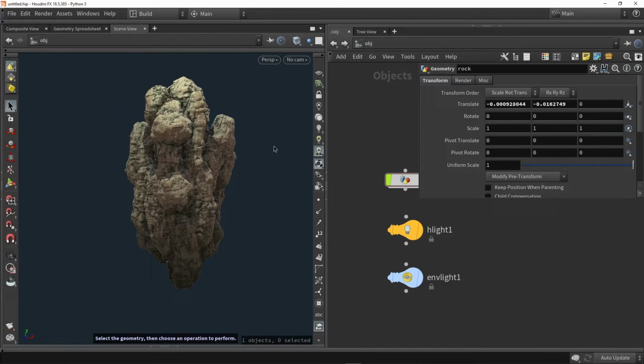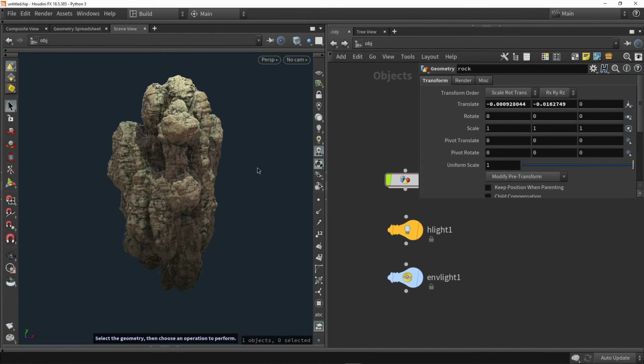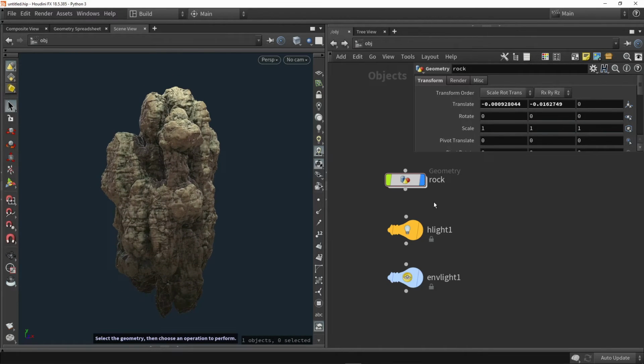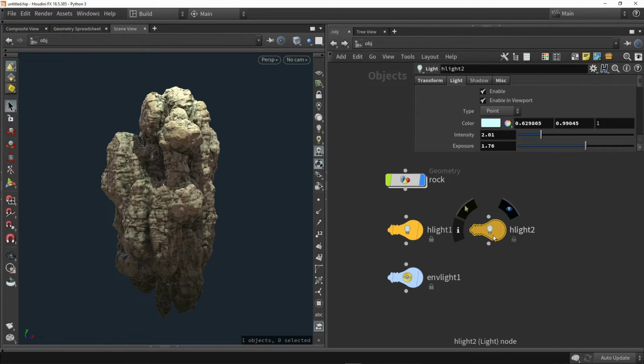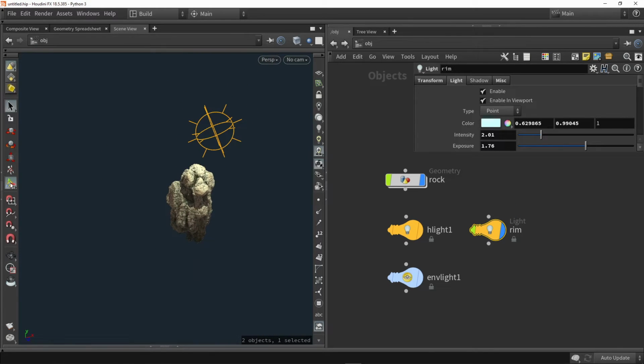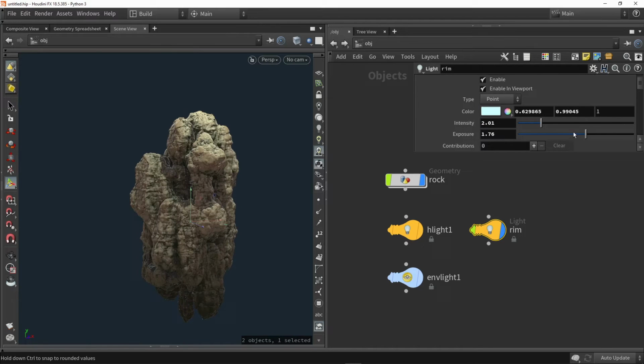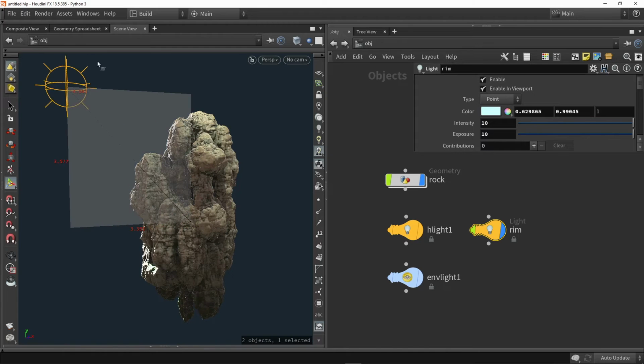Now I've covered some of the main settings here that can be interesting for your viewport to make it a bit nicer. And let's say I want to quickly make a really nice screenshot of this. I'm going to, for example, make more lights. So we can add a rim light here. So, rim. And let's of course enable these tabs back here. So I can grab my light and place it in the back of my rock. And I'm going to increase the intensity a lot. So let's just crank that up and see when we start to see a rim light.